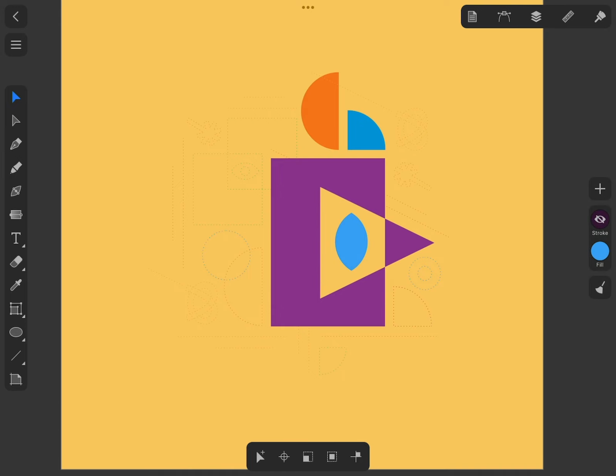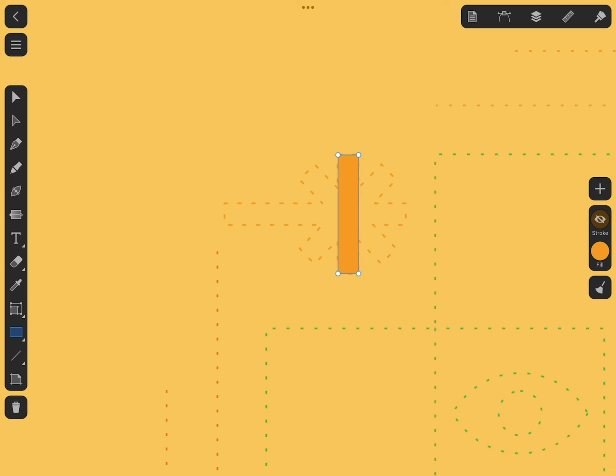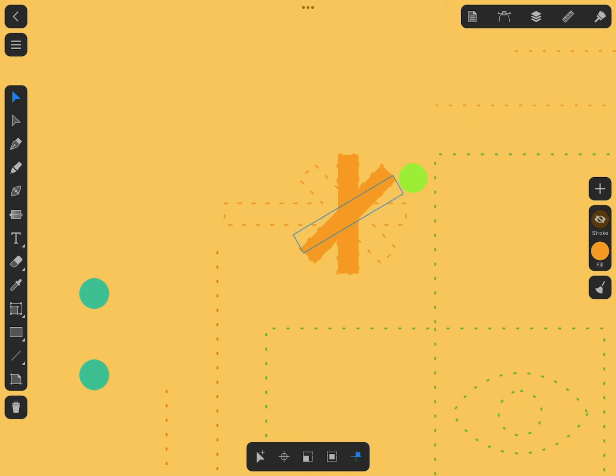To create a propeller stick, let's start with drawing a rectangle, a slightly elongated one. Then switch to the Move tool and enable the Constrain option to constrain rotation to 15-degree increments. Select the rectangle, and holding down two fingers, drag the rotation control to create a copy of the rectangle positioned at 45 degrees with respect to the original. Repeat this until you have 4 rectangles that form a star.